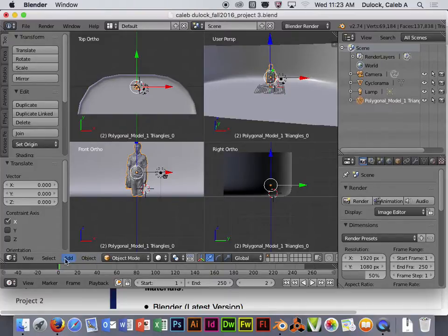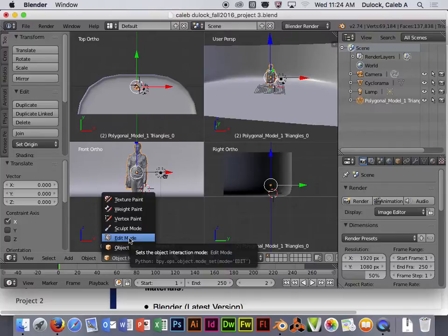If you notice along the lower menu inside of Blender, your lower 3D menu has that orange cube icon and it says object mode next to it. That's the basic mode for translating, moving, and rotating objects. But if you click on that button, you can also access some other modes. There are really only 2 other ones that I want you to focus on in terms of playing with in this project, and we'll look at those today. Edit and Sculpt. So we're going to start in Edit. So switch to Edit mode down at the bottom.